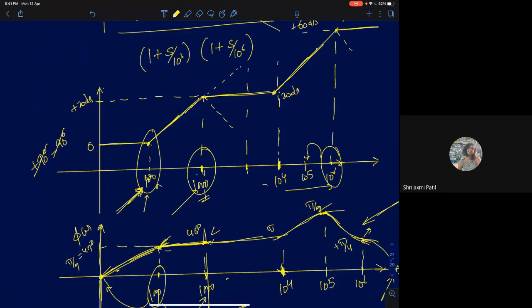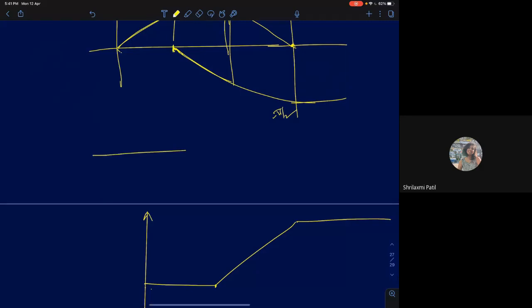Now what I said is, look at what is the effect of the two. You have a 0 at 100 and you have a pole at 1000. Now always remember, whenever you are drawing the phase response, whether it's a pole or a 0, if you know the location of a 0, the phase response will start kicking in a decade before. You should look at a decade before this, omega z by 10, and it will last for 1 decade after this. Magnitude response will last forever, but phase response will last only a decade before and a decade after.